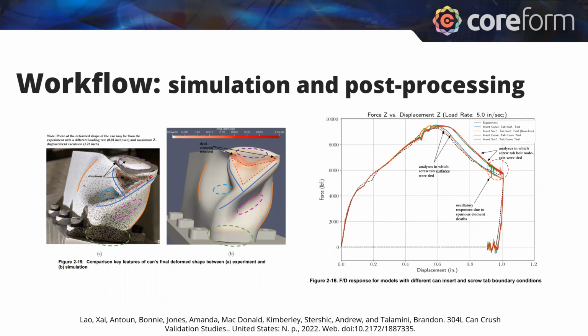But then especially as you're actually doing engineering work and you're optimizing, you put a probe on a fillet, and now I'm just going to track, as I change the radius on this fillet, what does the stress value do? And what radius do I get underneath a certain stress value that I need to have? So being able to do both plotting of 3D graphics as well as plotting and analysis of time history data is valuable.